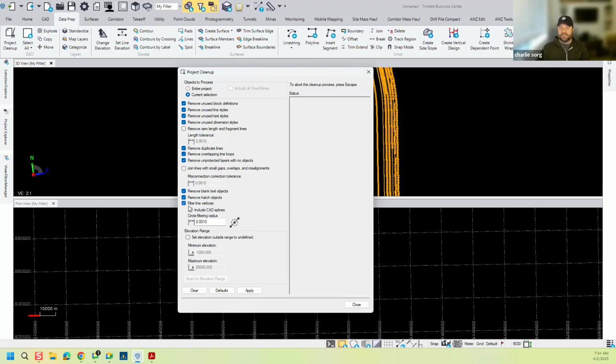If I set this radius large enough, it would remove maybe my high point or my low point on those back curves because they fell outside of this filtering radius. That's the kind of issue I'm talking about, where you get unexpected results. It's certainly not doing anything wrong. I told it to do that, but that's not what I wanted it to do.